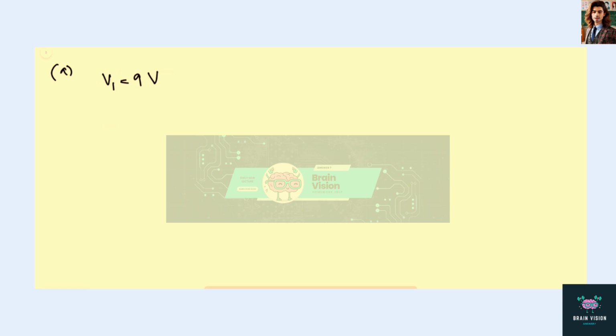So this is Ohm's law for the voltage across R1, and I is the current flowing through R1. So I will be equal to V1 over R1. Similarly, by Ohm's law, we can write V2 to be equal to I R2, where V2 is the voltage across R2, and since they have the same current, we are using the same notation I.